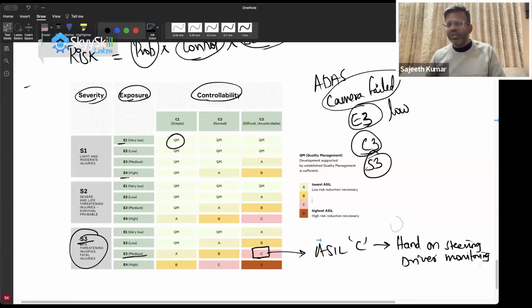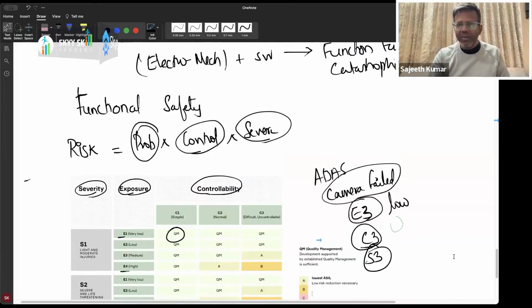So what we try to do is, as we introduce more software into the vehicle, we should not make the vehicle extremely failure prone. We should think about what are the failures that can happen. We should try to think about how we can design this particular system so that even if failures do happen, it is failing in a safe mode, right? So, which is why an adaptive cruise control will only activate when you have your hands on the steering wheel and you're looking straight. If you're not, then it will not activate. Similarly, if you touch the brakes, okay, now let me come back here.